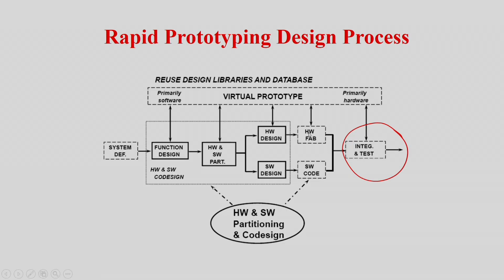Nowadays it's true that we have very large size FPGAs, but for many practical applications multiple FPGAs have to be used to design what is equivalent to a single ASIC. Because as we have seen, FPGAs are basically some kind of general purpose hardware. So the advantage of FPGA is that you can very quickly have a prototype, but the area will be higher, and at-speed testing cannot be done because FPGAs are generally slightly slower than your contemporary ASIC designs. But still some work has been done, or people are trying to emulate, or they make a prototype hardware and download the software and try iterating, so that bugs are debugged more easily, and by the time you go to the fab and finalize the software code, many of the design handshakes have been done. But again, it's a very, very challenging problem.